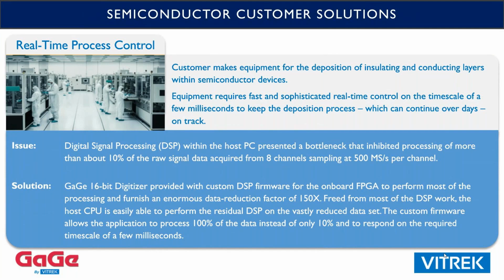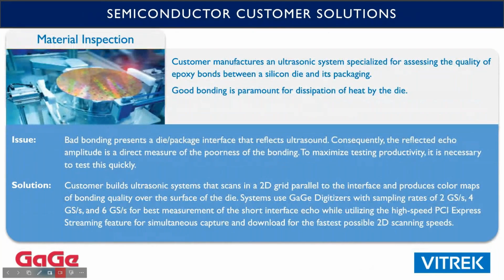So moving along from the fab process, the next stage is inspection of chips, of the dies, during packaging. So the next application here is an important one. One of the main functions of the package, other than getting the electrical connections on the die out to the user, is for dumping heat. So the silicon die, again chopped up from the fabricated silicon wafer, has to be well bonded to the package so that it can dump its heat.